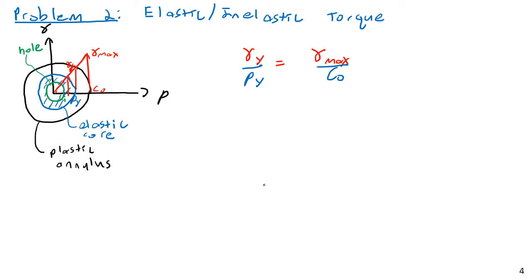So the maximum strain is going to be at the outer radius, but it's simply going to be a direct proportional relationship. The strain just linearly increases from the core all the way out. Although in reality, since we don't have any material in the inner core, there of course wouldn't be any actual strain or stress there.